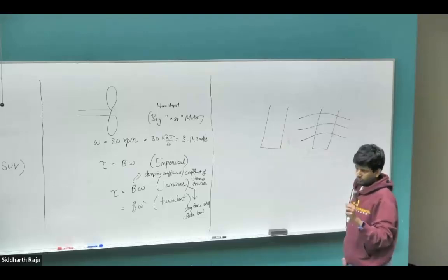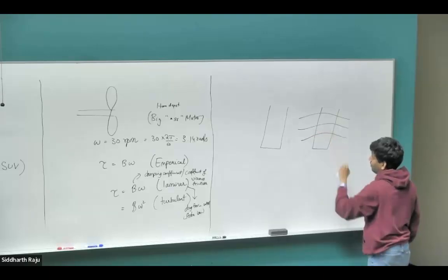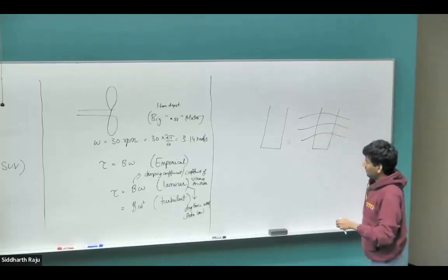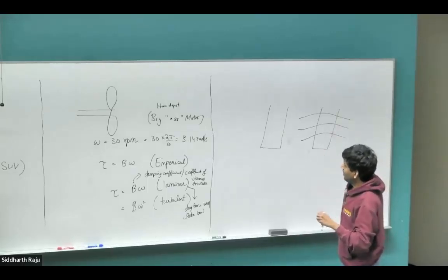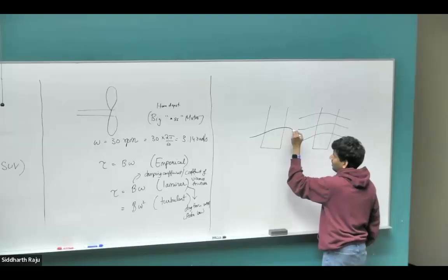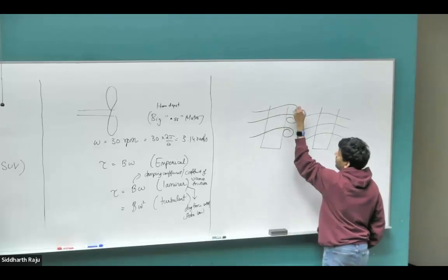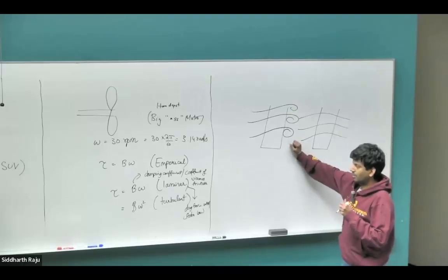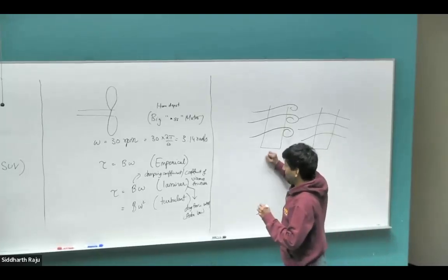But in laminar flow, there is a phenomenon called fluid separation, where after the air molecules pass through a portion of the blade, they start to separate from the blade and move away from it. This causes a precipitous drop in the lift that can be created, and the system becomes extremely inefficient. So typically these blades are structured so that the air molecules that make contact, as they exit, create vortices and become turbulent. This helps the air molecules stick very close to the blade, thereby improving the lift generated. So turbulent flow is intentionally created to help with lift.